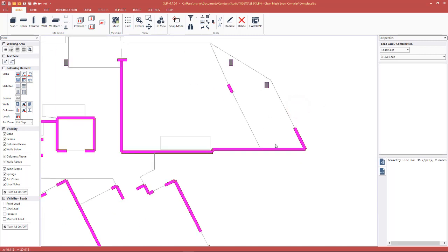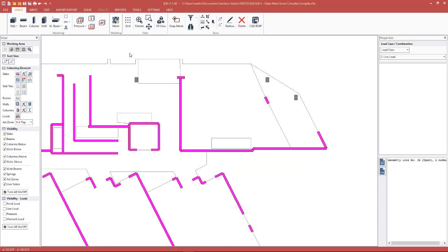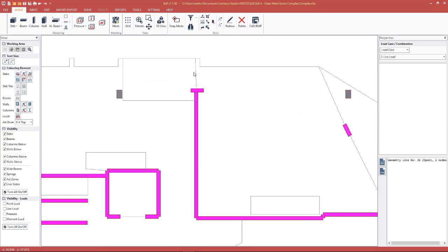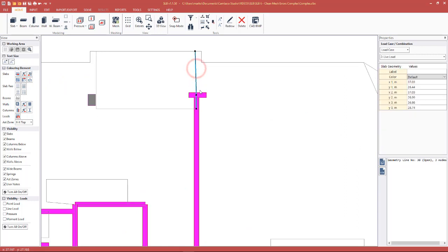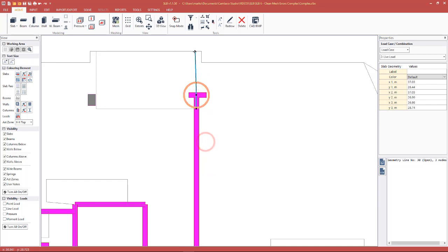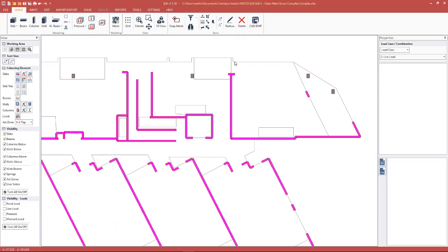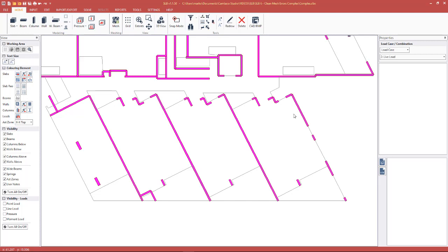So this area now should be fixed. It's also been simplified as well. And visually inspecting here, we can see that there's a slight kink in this geometry line, so we'll tidy that up. We will set that as a master and align that to the X. And no meshing errors there, but just to keep it straight. Pressing Shift-A on the keyboard to show the mesh. Despite there being no mesh, it will still show us the errors.